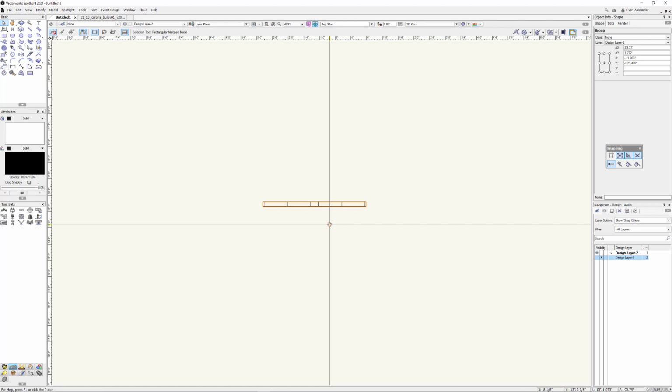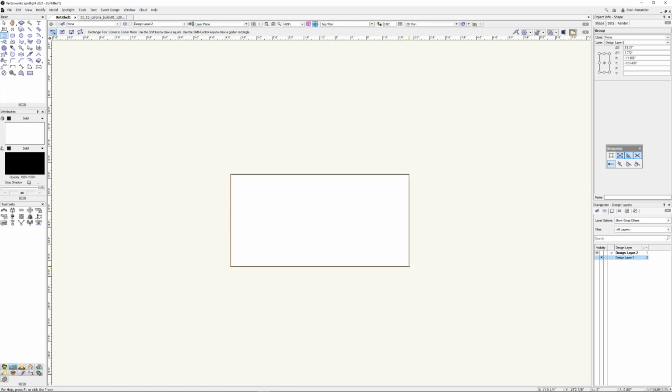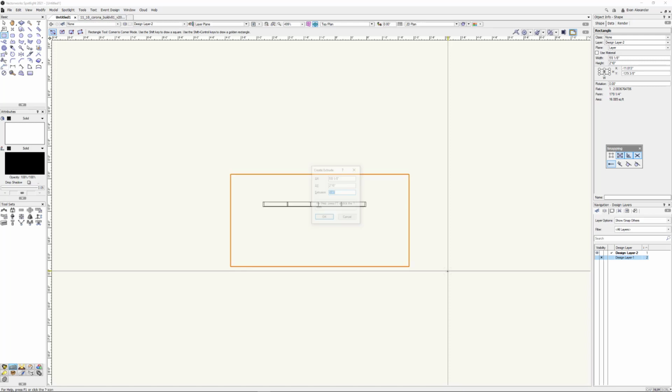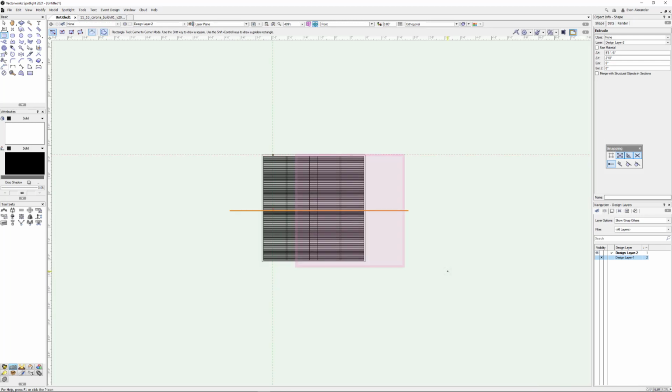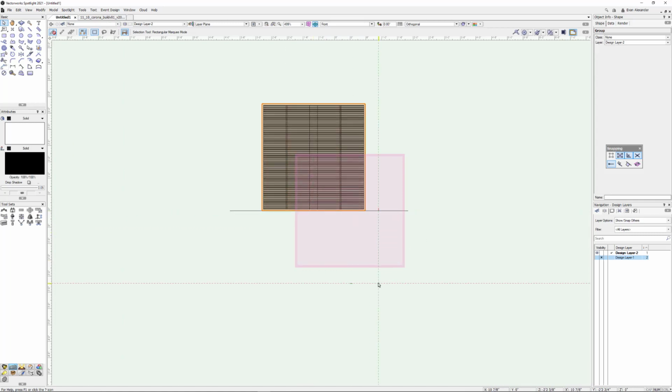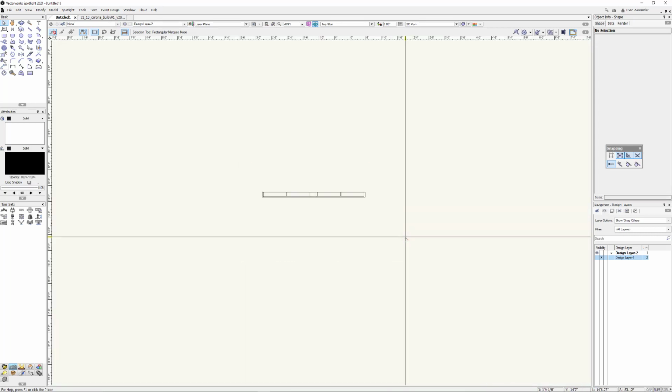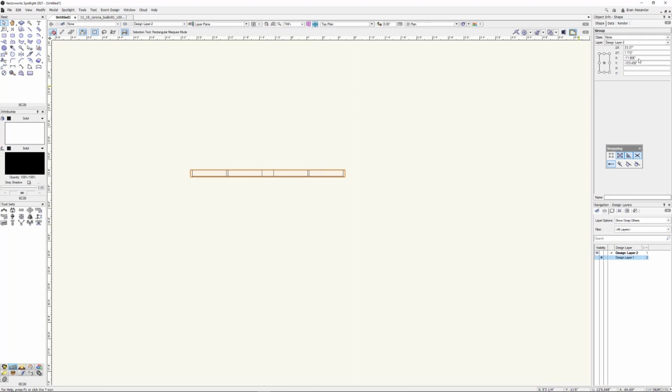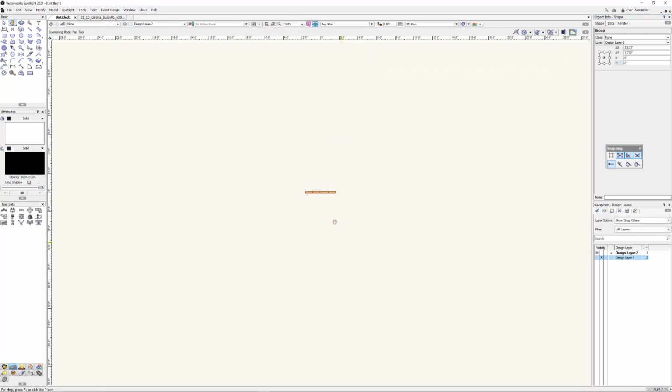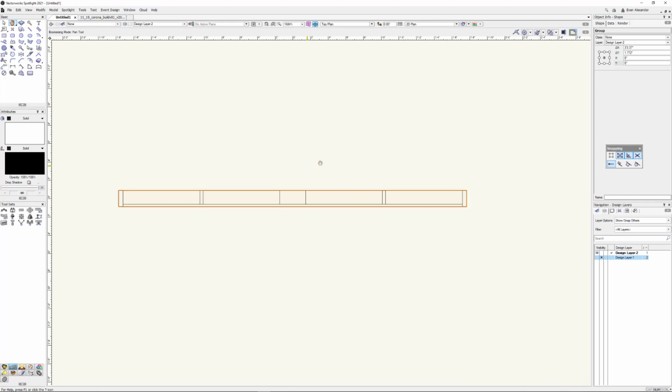And so just for good posterity here, let's draw a rectangle in top plan, and let's extrude this 0 inches. It's just like a flat polygon. And so now we know this is where the ground is. This is the 0 level. So I'm just going to take this and snap it to that. And we'll hit this and say, bye-bye. We don't need you anymore. And I didn't actually center this up in the world, but we probably should, just to be good, responsible citizens here. 0, 0, 0.